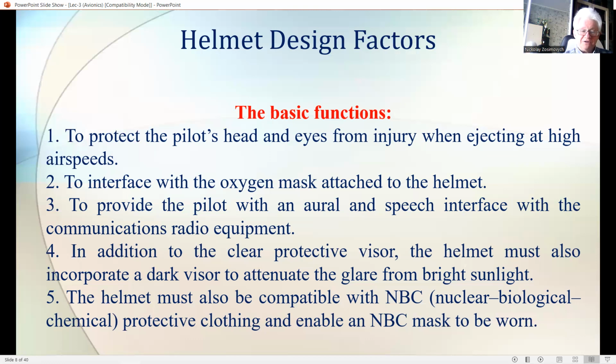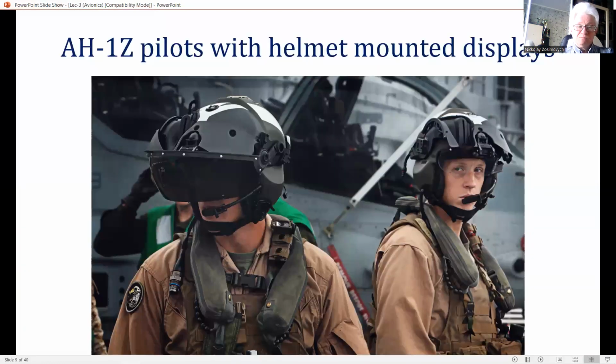The coloration effects from the coatings are also disliked by the pilot, and neutral density coatings are preferred. The optical system must not provide any visible join line, for example, should the two halves of a binocular system abut each other. This is to eliminate the possibility of such a join line, even in vertical, being mistaken for the horizon during